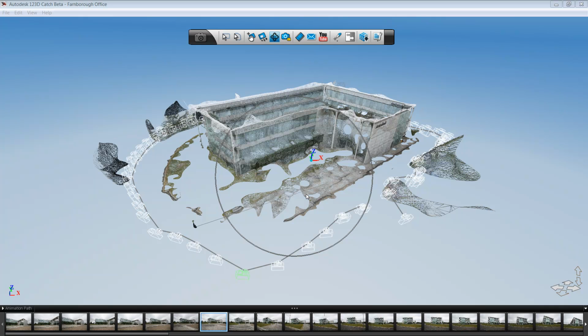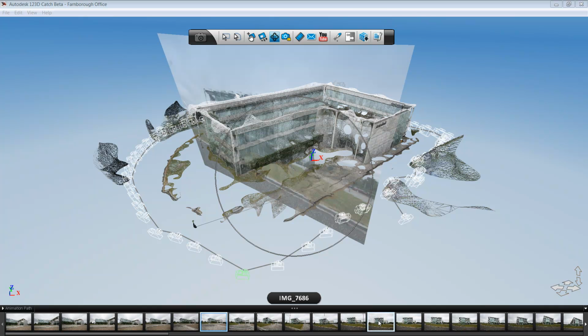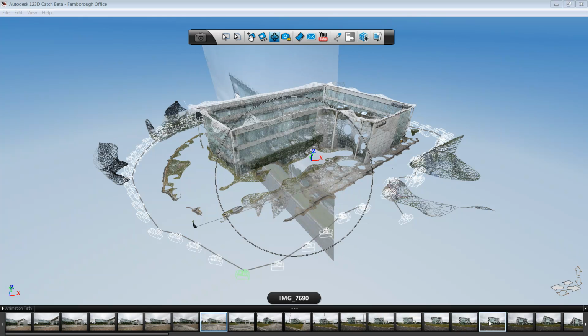Autodesk Photoscene Editor plays an important part in the rapid energy modelling process, especially with existing buildings where no documentation is available. Here we've taken photographs of the Autodesk Farnborough building, and we've done about 70 around the entire building. We've done that also with a wide angle lens, and it's very important, even when you can get the whole building within a photo, that you do make sure you've got plenty around the entire perimeter with lots of overlap.